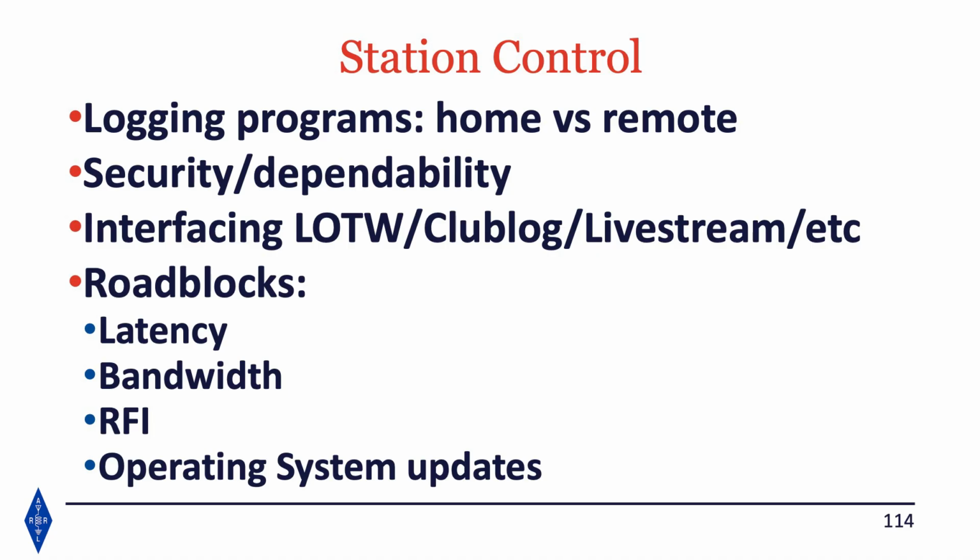It's all of that, and it affects things. Another thing is that things will stop working in RFI problems, and it's very hard to troubleshoot because you're not there when it happens. Something that we've learned finally: some subtle change at the site, they changed the way the power was routed into the building, created a massive pile of RFI problems, and we had to go out there with sacks of ferrites and snap them on everything, and it stopped. We have no idea what fixed it, but we don't care. We have fixed it today, and we have bags of ferrites out there when it breaks again, for whatever reason.